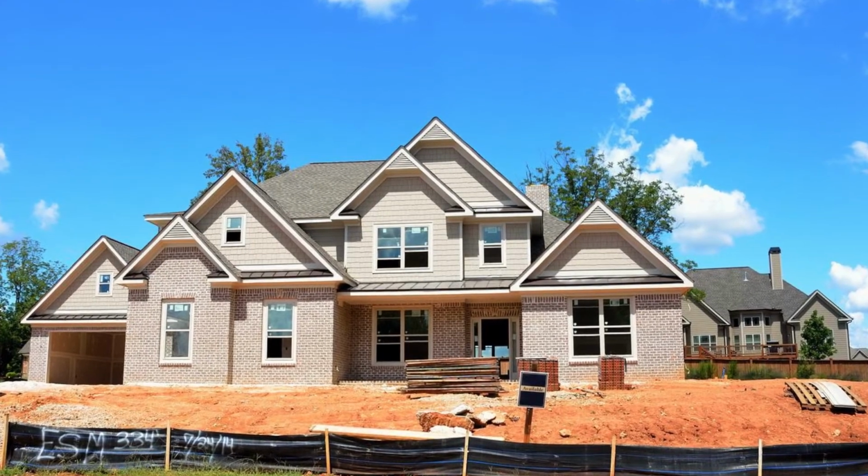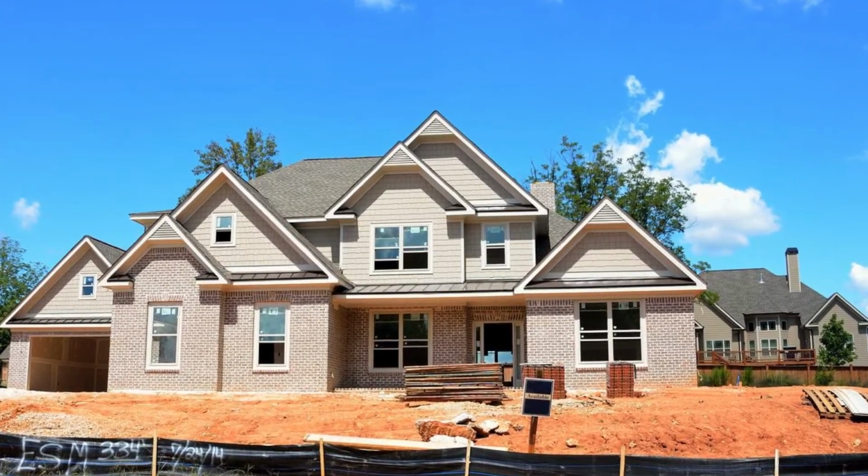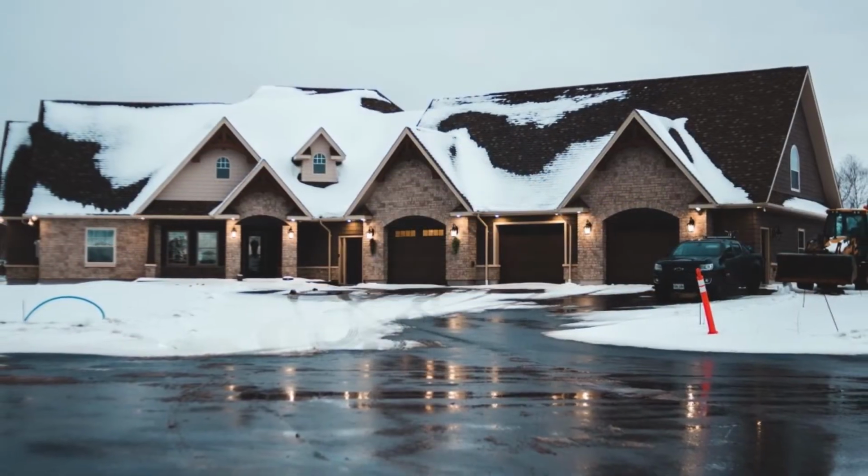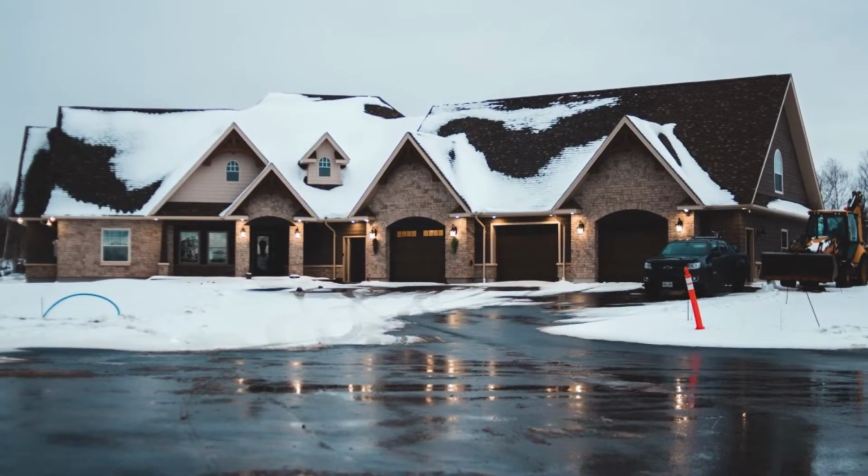How often have you heard people being complimented on how nice their roof line is? Roofs that have unnecessary valleys, they're all opportunities for ice and snow, possibly leaks, or opportunities for flying embers during a wildfire to land and catch fire. Also where moisture accumulates and moss and lichen will tend to grow over time and then eat away at the roof. Simpler roof, simpler building form.